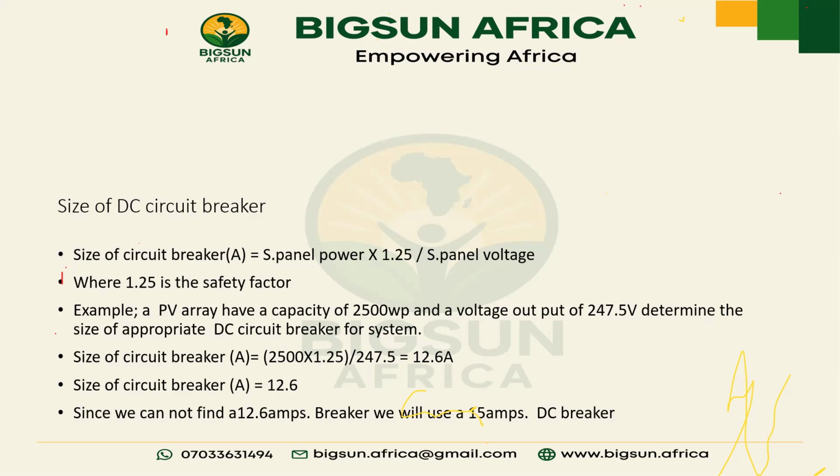Due to my own experience on this job, there are some panels, though sometimes you do get sticker panels, and there are even some panels that state their VOC. But during sunshine and rain periods, some panels used to shoot up even above their VOC. I've witnessed that before. That is why, if you look at the panel, there is always a plus or minus 5%. Yes, sir. So that's why I'm saying maybe you should consider the VOC to be on the safer side.